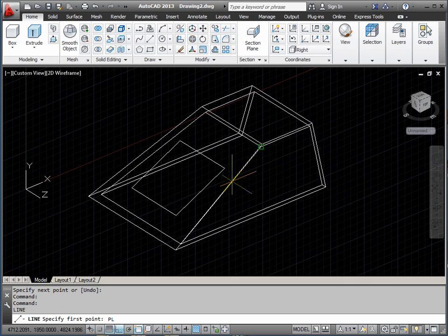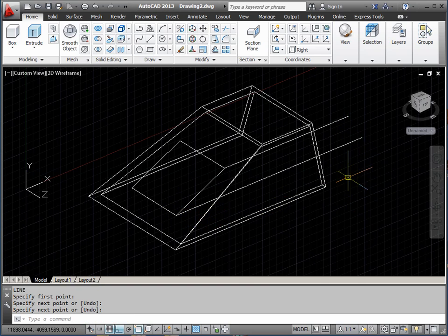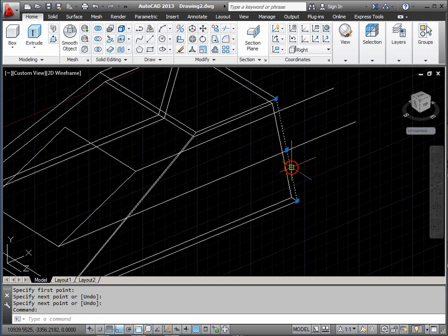But now use a polyline from the corner of the window. And this won't change its Z coordinate. It will stay in line from where we pick. So I'll take a polyline there and a second polyline across here. Okay, so we've got a line there that can be trimmed by these two polylines. Even though they're at a different depth, they're further back than this line.